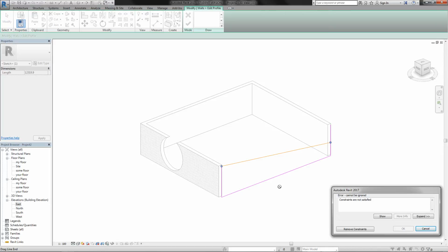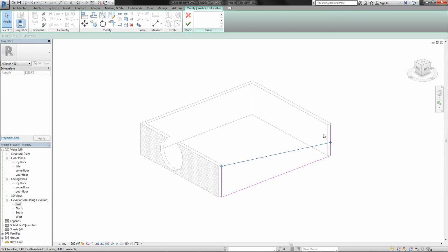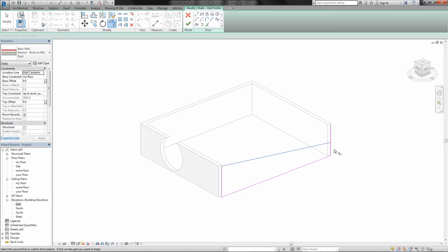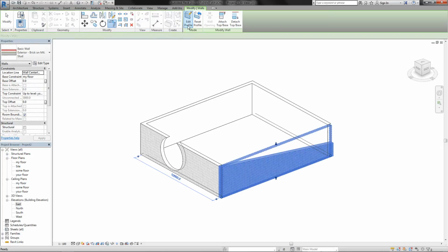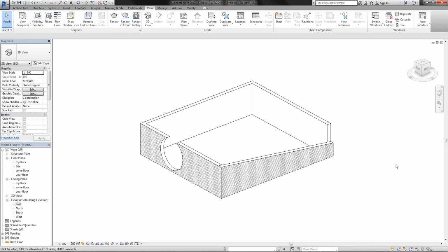So as soon as you unjoin two walls or two lines or something like that, it will tell you, hey, you're doing that, or make sure you're aware of what you're doing, or if you want to stop you from doing that. Or if you move a door or a window outside of a wall, it will tell you, hey, there's no wall to build a window in, I will delete it. And say, okay, I will delete it for you. So I would say remove this constraint and let me do what I'm doing, and it will do. And I will define that's an angled wall, it will have it, and then that's my wall. So you can do that kind of thing, which looks kind of dumb, but it will get more interesting than that.